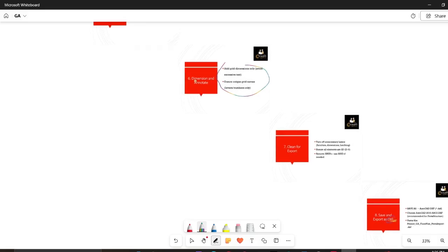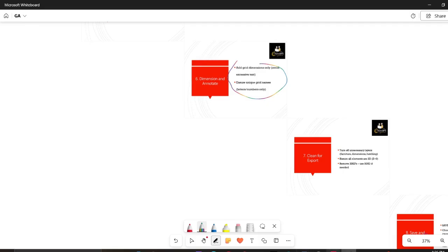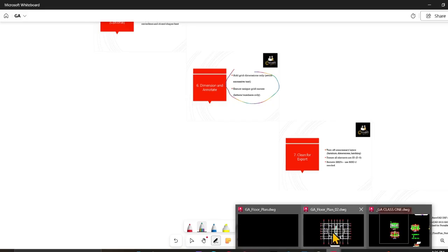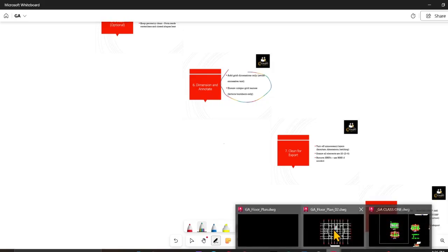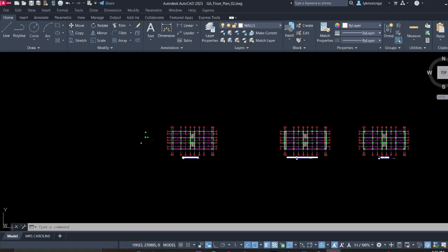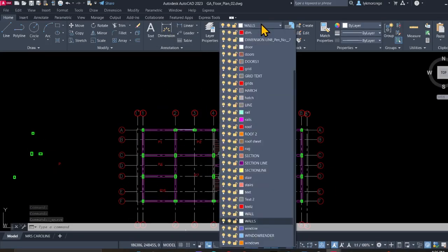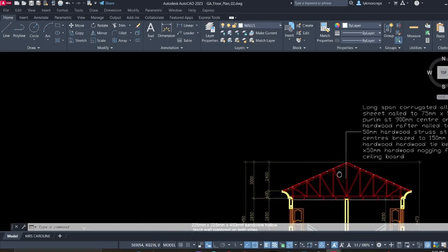So with that, you can see here they are saying the dimension and orientations, but not very necessary at the moment. But if you really need them to be in place, you can actually do that. So to do our dimensions, just open our ProtaStructure here, and then remember to save our model. Once we save this model, just come to walls here, ensure that you check which layer was given the dimension layer, and simply come to check.